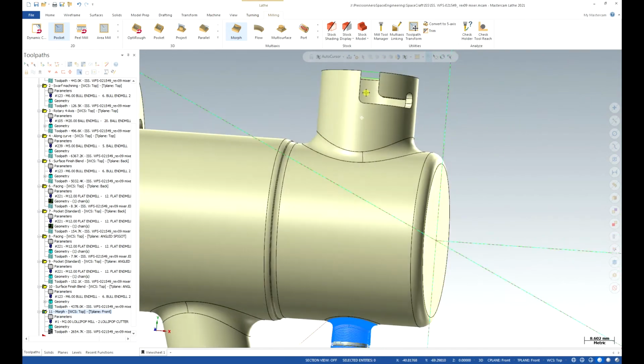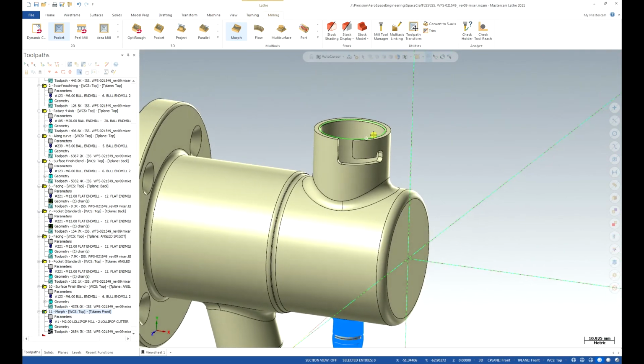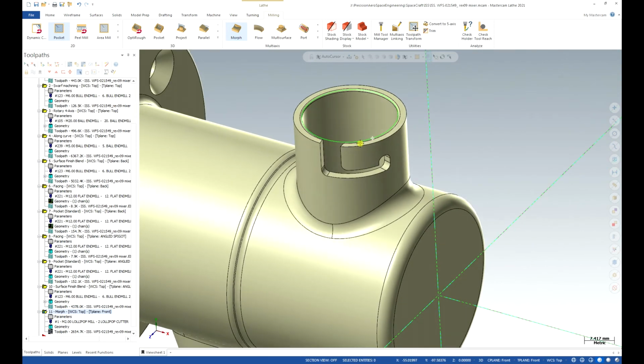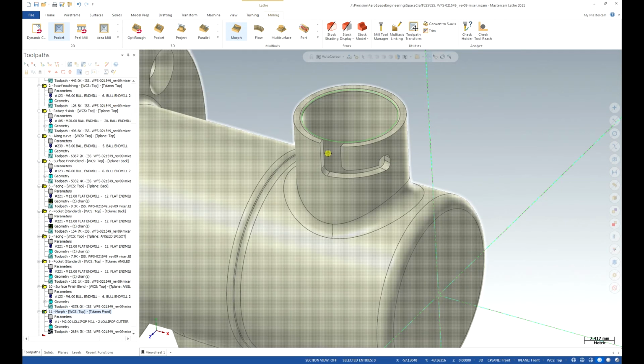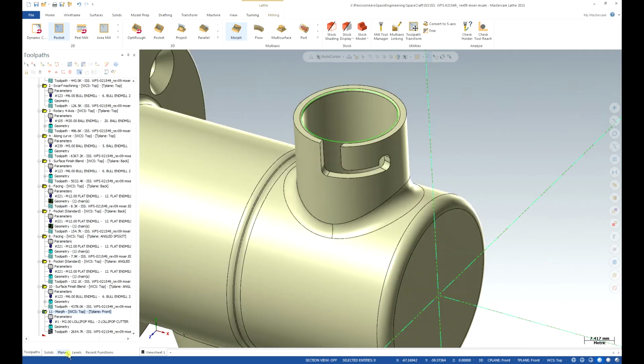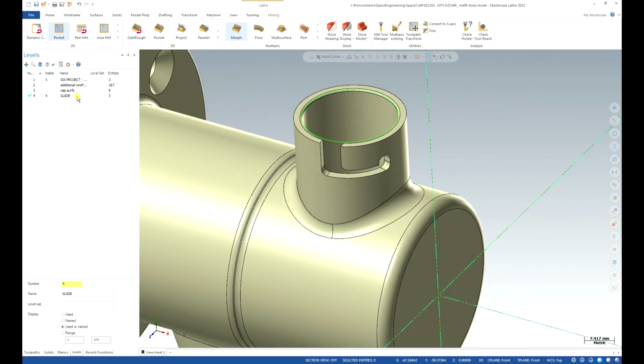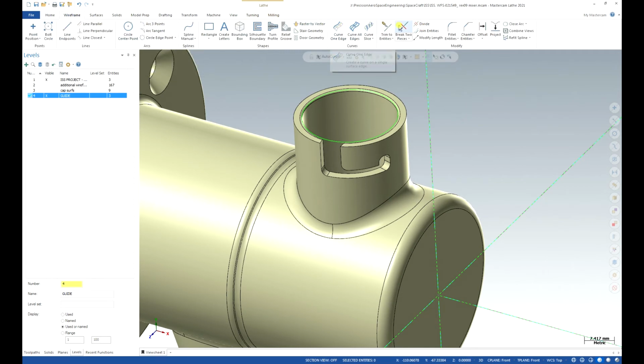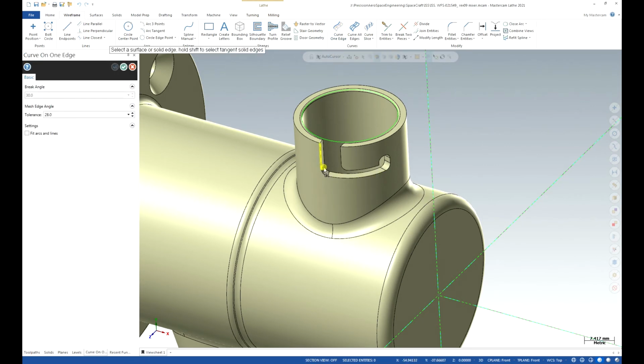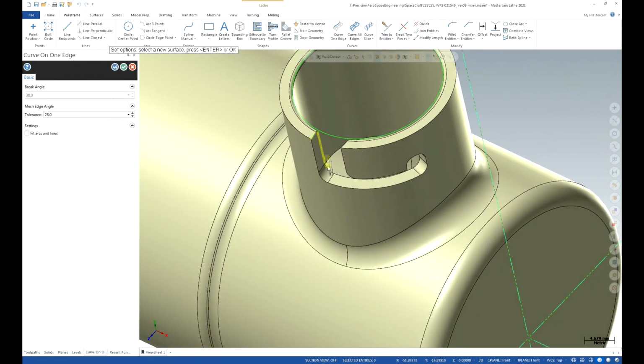Okay, our next toolpath is going to be a Swarf multi-axis toolpath, and this toolpath will use the side of the tool to cut selected drive surfaces. So let's make active our level width guides just to create additional geometry for tool control, and we are going to create lines which we are going to use to control our tool axis, tool tilt during the cut. In our case, I'm going to use the edges between the surfaces.